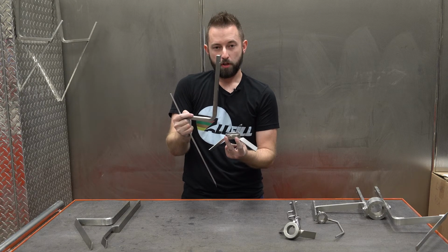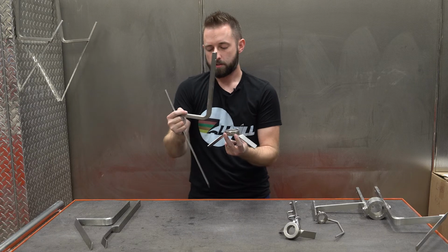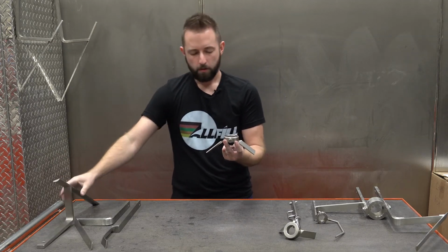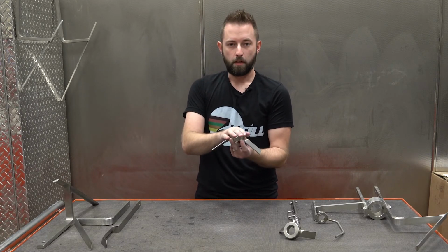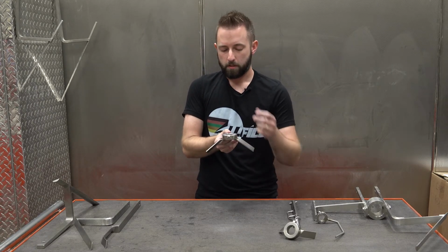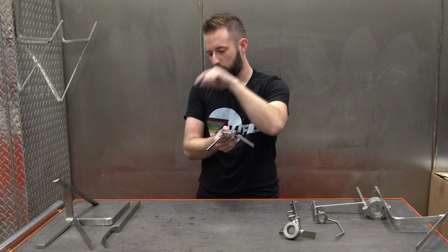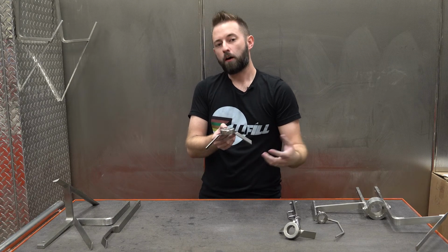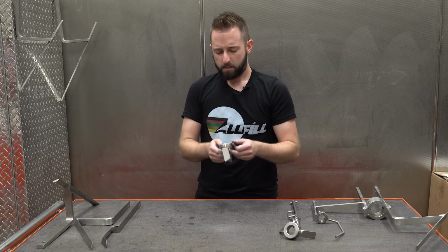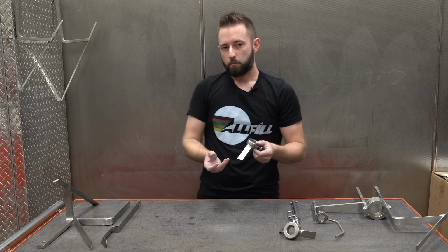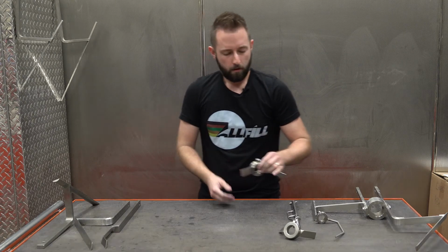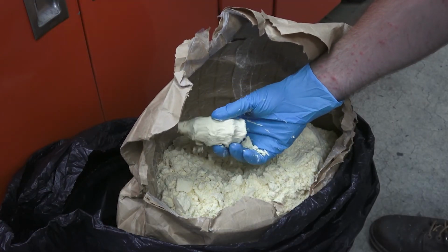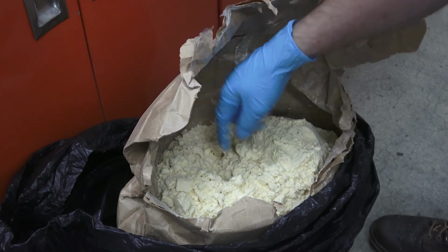This mounts in the auger shaft directly above the auger. So as this is sweeping on the outside edges, delivering product down to the center of the hopper, this is spinning at the same RPM speed as the auger. And what it's doing is it's helping grab that product in the center that's being delivered from the slow speed agitation. It's grabbing it and forcing it down into the overflight of the auger that's delivering product. So a good example of this is a very fatty, moist cake mix, brownie mix, things like that. These are absolutely integral in getting a really, really solid efficiency out of those augers with an incredibly non-free flowing product.